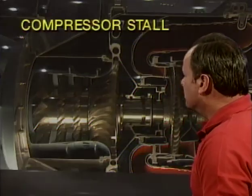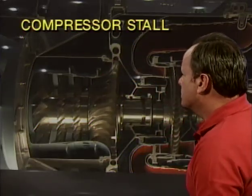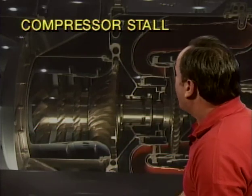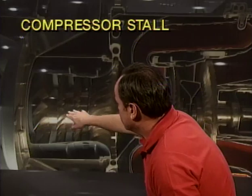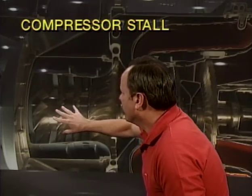Now, if you don't maintain smooth engine operation or you have contaminated blades, you could have compressor blade stall. And compressor stall, as we said earlier, is a bad thing, and it's caused by high angle of attack of the airflow, generally on the first stages of compression here, and these blades would begin to stall here, and that would be a very bad thing.